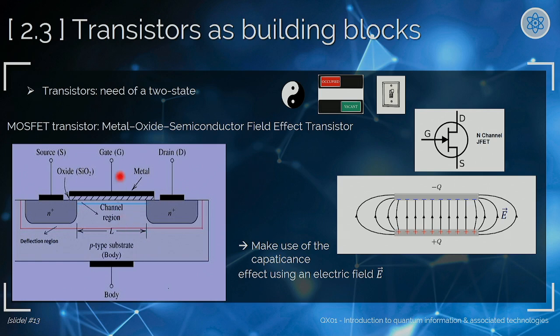When you switch on the gate, you create an electric field that gathers at the surface here, moving the charges and gathering electrons at the surface. Of course, they cannot channel through, because you have this small oxide layer, which is an insulator layer that's not going to let the current through.